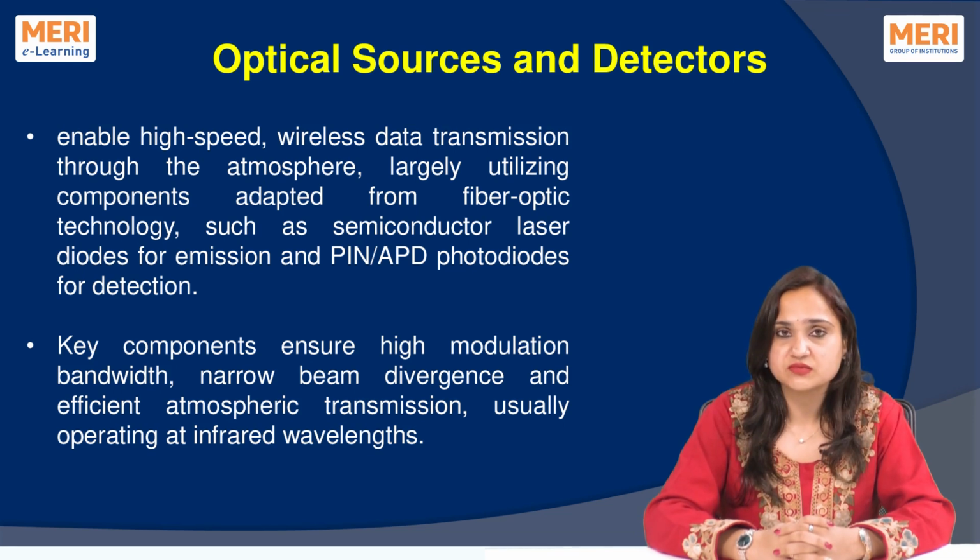Most FSO systems operate in the near-infrared wavelengths such as 850 nanometer, 1310 nanometer, and 1550 nanometer. These wavelengths minimize atmospheric scattering and take advantage of the mature fiber optic technology. The 1550 nanometer wavelength is particularly preferred due to its lower atmospheric attenuation and better eye safety characteristics.